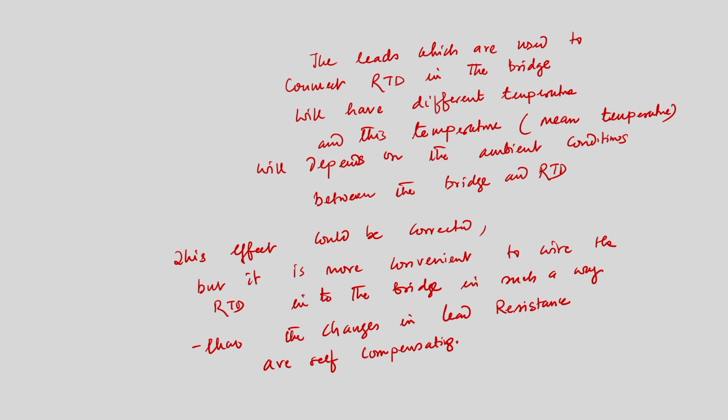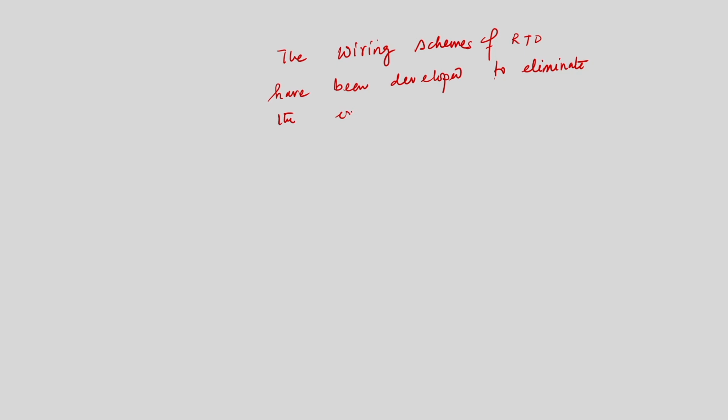Based on this, the wiring schemes of the RTD have been developed essentially to eliminate the error due to the changes in lead resistance.